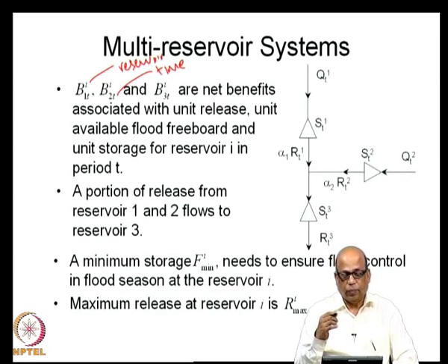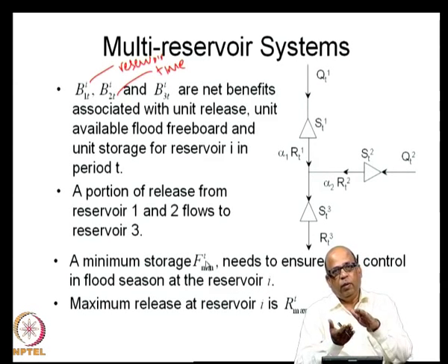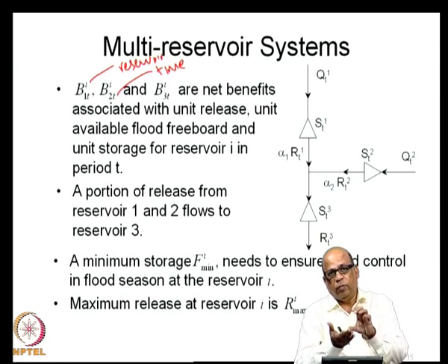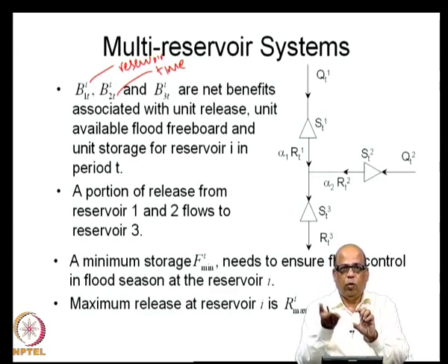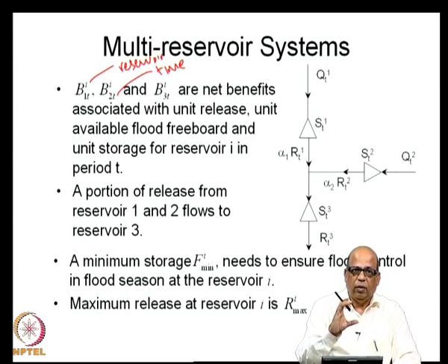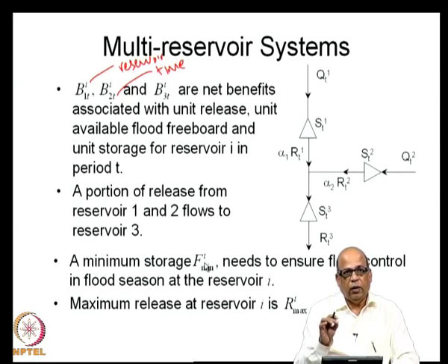So, we want to make sure that a minimum storage of F min I is at reservoir I, a buffer storage, which means that the storage level should not be more than a certain point, so that you have adequate buffer to absorb the flood waters, and that is what we are indicating here. At each of the reservoirs, we specify that during this flood season, which may be different for different reservoir systems, we want to retain a certain flood freeboard.